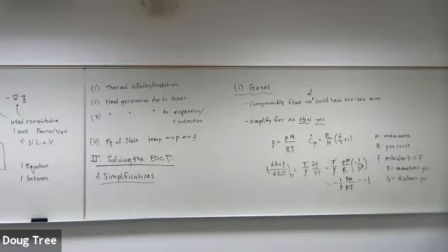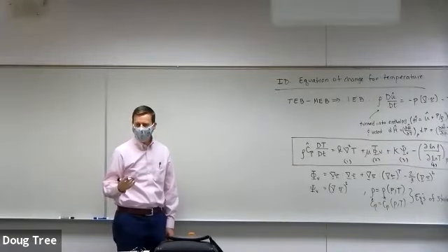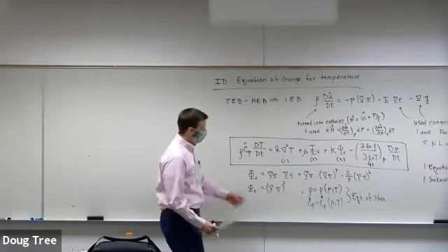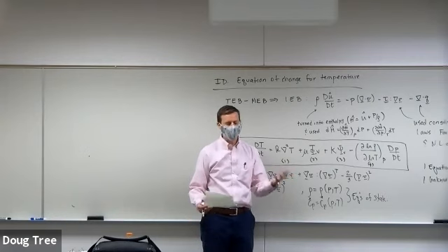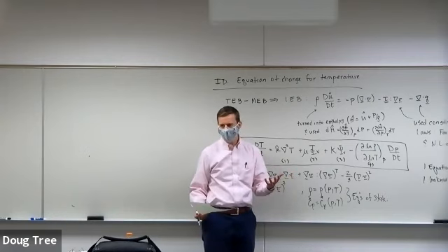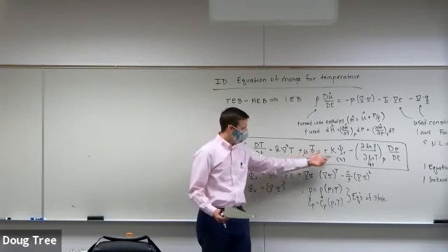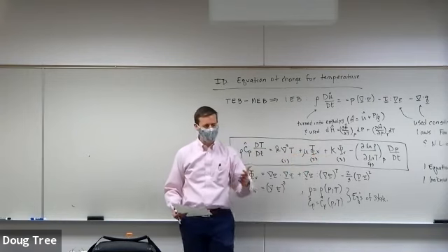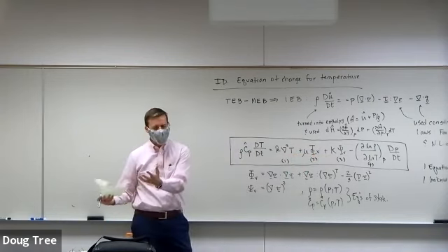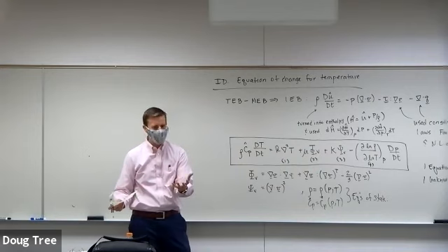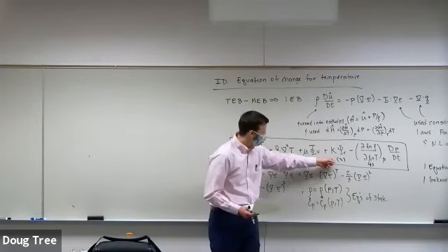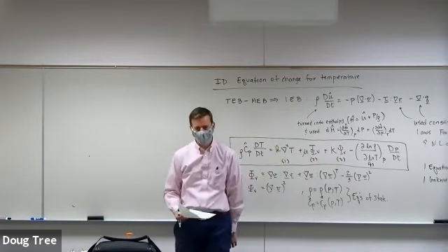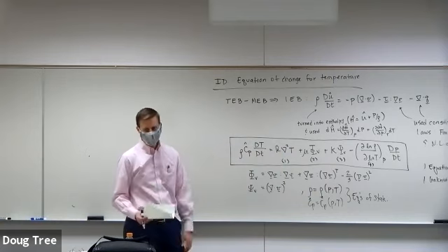The other thing that happens in a gas, if you remember, is that the viscosity is usually really small. We're going to see in dimensional analysis in a little bit that we can get out dimensionless numbers for these guys. It turns out the velocity gradient times the viscosity has to be big for that to matter. And so we'll find that these two terms, 2 and 3, really aren't going to matter very much unless our viscosity is big.